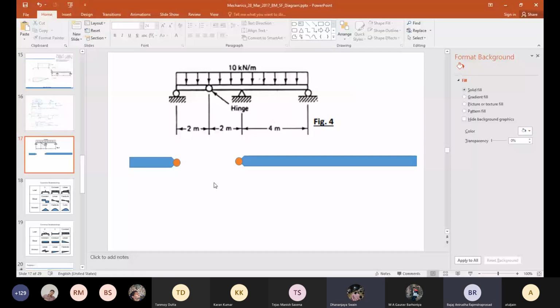Sir, the roller joint at that part, if you are going to find out the force, then at first, without removing the hinge part, can we calculate it? No, then it is statically indeterminate. Look at the number of unknowns. There are 4 unknowns.